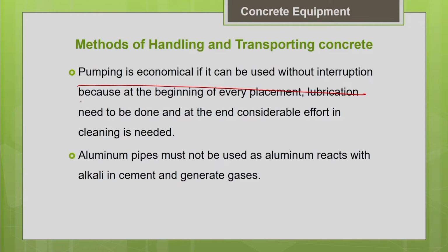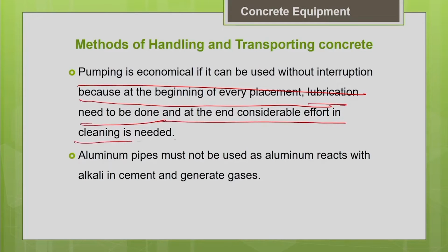Because at the beginning of every placement lubrication needs to be done, and at the end considerable effort in cleaning is needed. So, that is why if you need a continuous supply of concrete, continuous placement of concrete, a steady supply is needed. In that case you can go for the option of pumping.